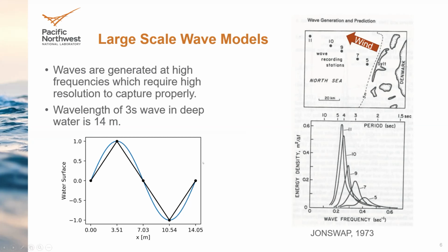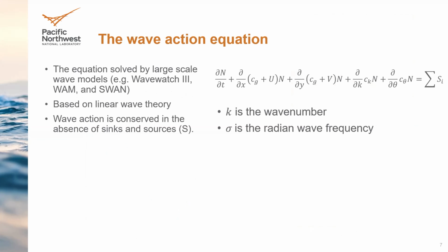So what we do is work in the frequency domain and talk about the energetics of the sea state instead of the single wave. Here's an example of how it looks. It's a very famous experiment offshore Denmark when the wind was blowing offshore, and there were wave staffs in these 5 locations. When you compute the spectrum here, you were able to reproduce in frequency space how the sea state was evolving, and that's the idea behind all the major wave models.